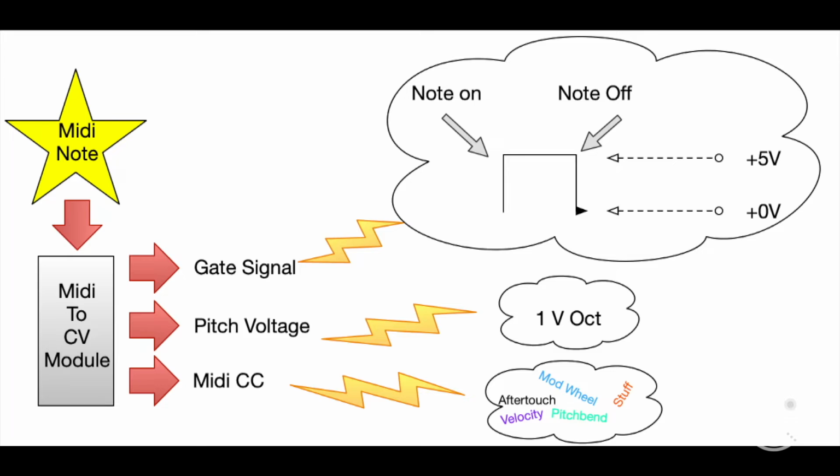Additional associated messages can also be converted to these control voltages, including MIDI velocity, aftertouch, and of course, modulation and pitch wheels. Each of these messages can generate its own voltage output. Releasing the key sends 3 more messages, including channel, note, and release velocity.